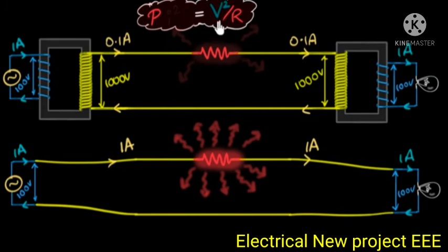Alright. Remember where this comes from. This comes from Ohm's law by substituting V is equal to IR. And Ohm's law is always applied across a resistor. So this voltage is not this voltage or this voltage. This is the voltage that would come across the resistor. And that voltage is basically I times R, which means over here, since the current is 10 times smaller, even that voltage across this resistor has also reduced by 10 compared to the voltage over here.